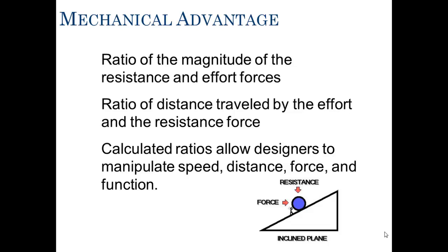So the resistance is the load, it's what you're doing the work on. The effort is what you supply, so it's you pushing, in the picture there, the boulder up the hill. All right? It's also a ratio of the distances traveled by the effort and the resistance forces. And you'll notice there in the opposite order. The ratio of the forces, we said resistance and effort. Then when we were talking about distance, we said effort and resistance, and it's because they're upside down.